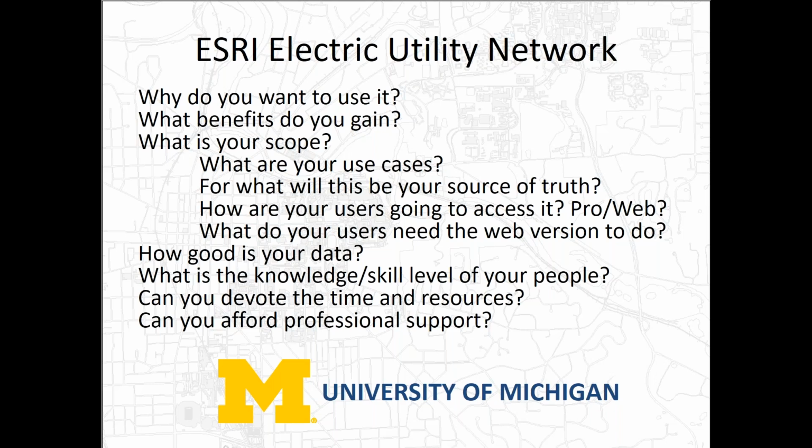Another piece is how good is your data? The utility network doesn't like things like dangles and crossovers, other pieces of data like that. If you're in a network already, you've got to step up. It's not near as hard to transfer because there's not a lot to clean up. If you're not in a network already, then there's a fair amount of cleanup that you're going to need to plan for and to plan your time for.